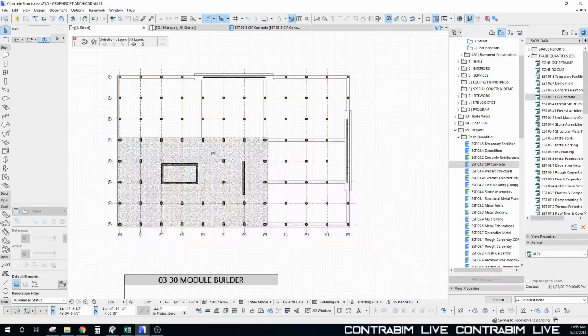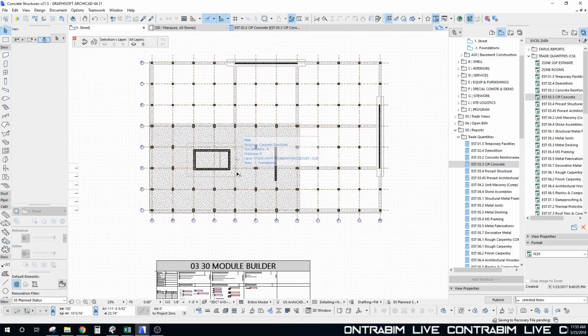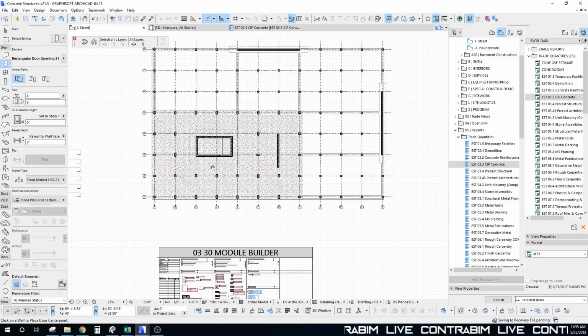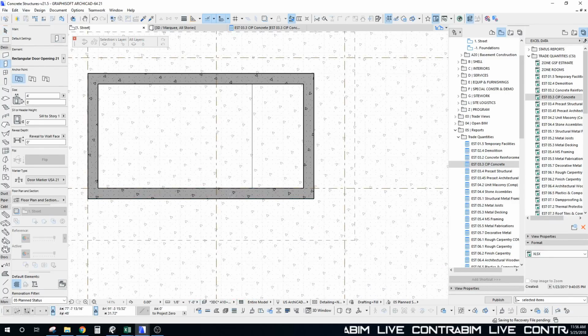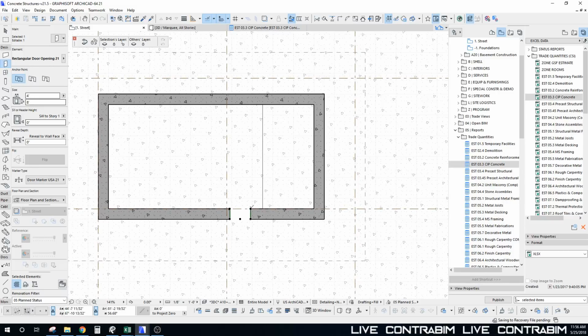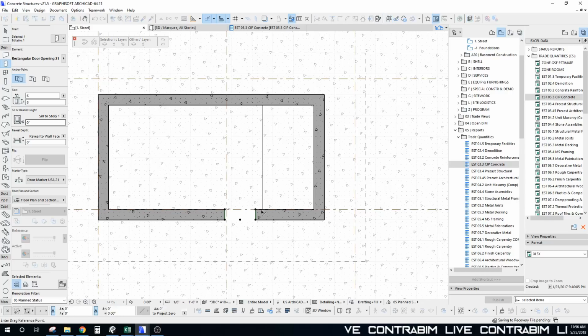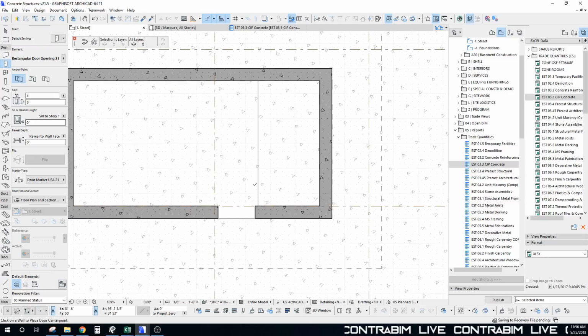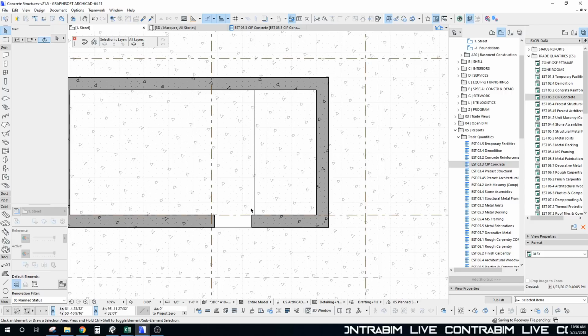and we're almost to the point where we can just fly through this thing and crank out the rest of this tower. But let's add a few things in here just before we continue up. So one of the things I'd like to add into these cores is a few openings here for the doors going into our elevator and stair shaft. So I'm going to give it a 6 foot there, and I'm going to just essentially offset this about 6 inches, and I would typically have a shaft wall running right through here.